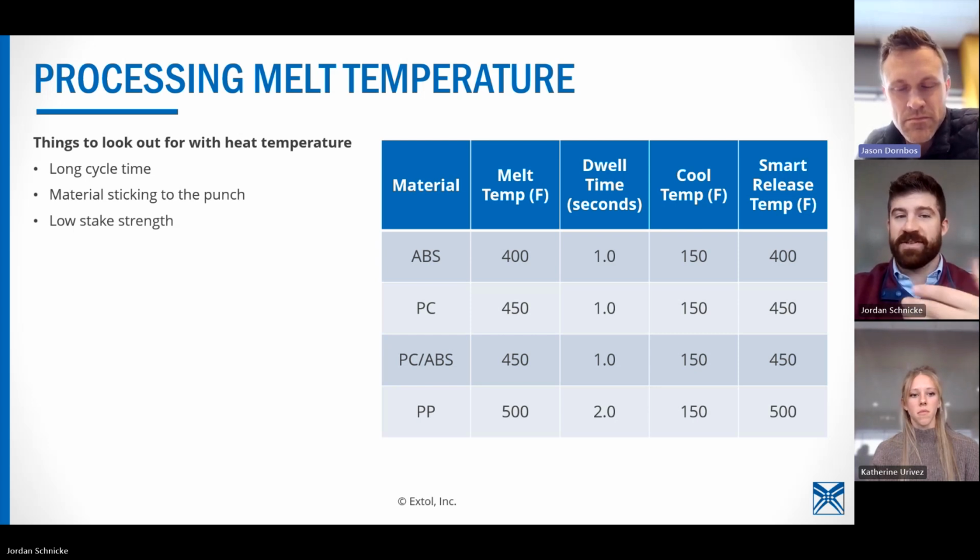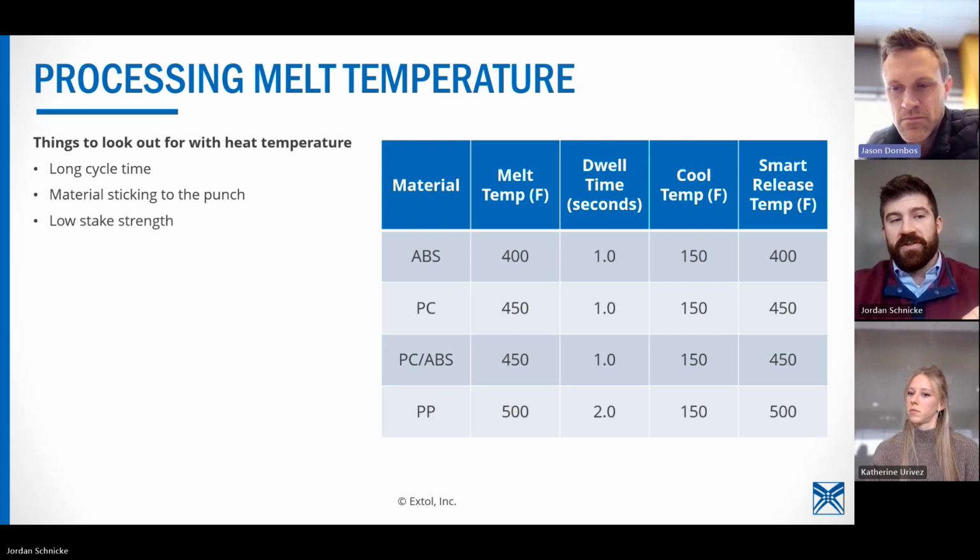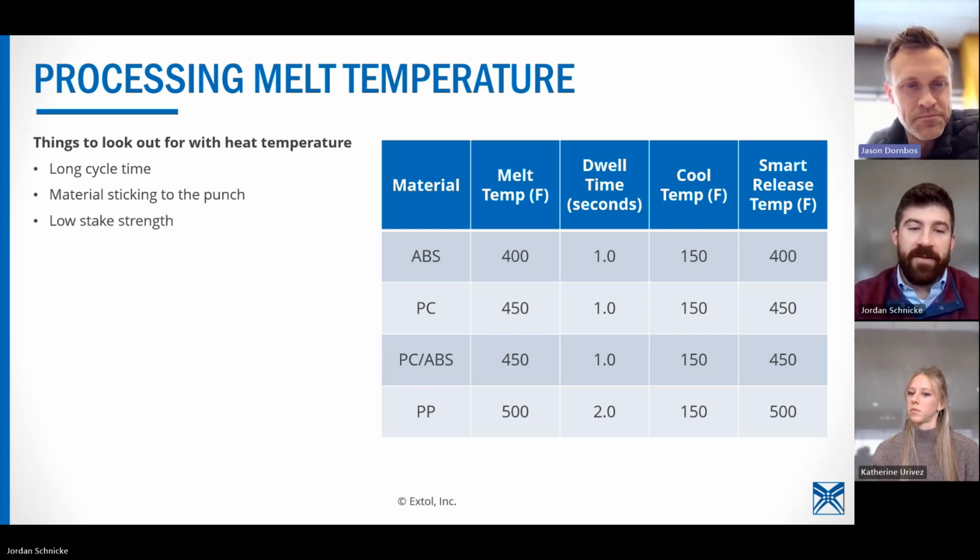How did it run? Is it sticking? Did it improve your cycle time, or did it not make any difference whatsoever? If you increase the temperature and you didn't do anything else and it didn't improve your cycle time, it would lead you to the idea that, hey, maybe my position is too low, maybe I'm overdriving. And there's other ways to verify that, simply looking at the finished product, but that's the one I would say I see the most often.